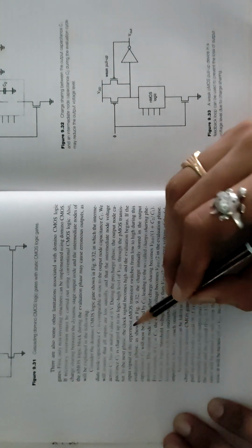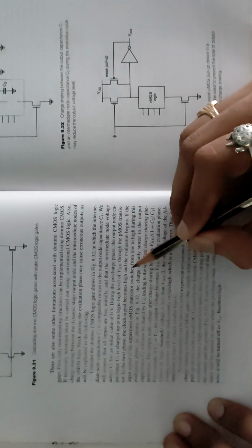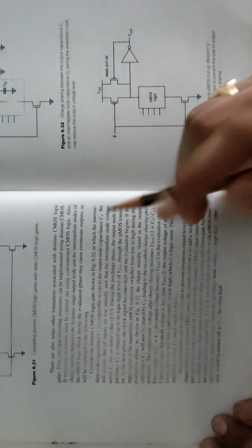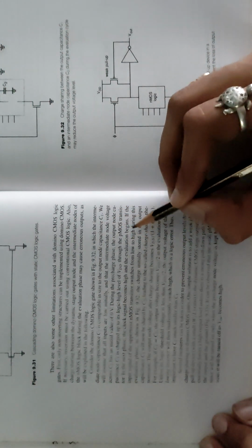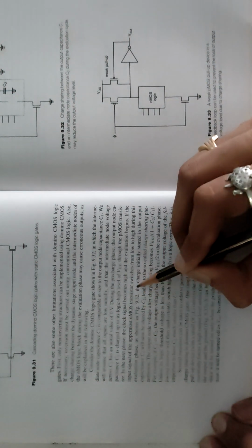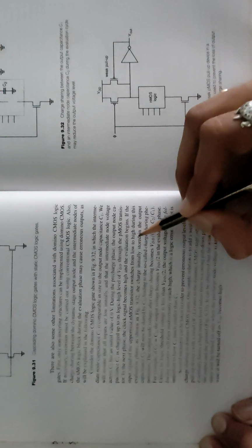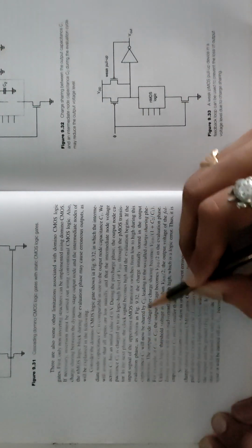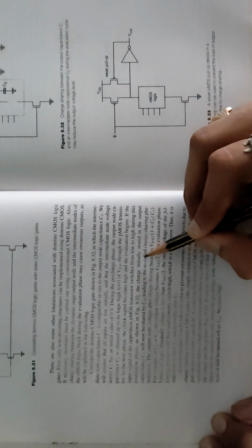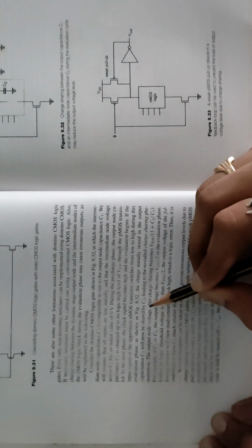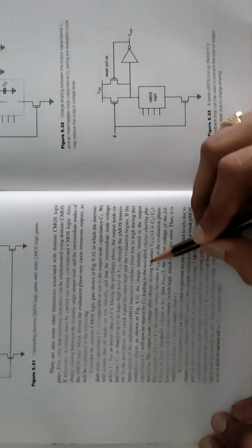In the next phase, the clock signal becomes high and the evaluation begins. If the input signal of the uppermost NMOS transistor switches from low to high during this evaluation phase, as shown in figure, the charge initially stored in the output capacitance C1 will now be shared by C2, leading to the so-called charge sharing phenomenon.